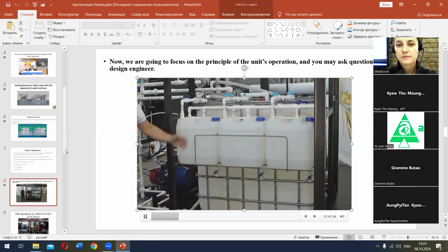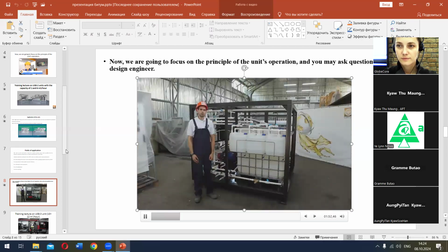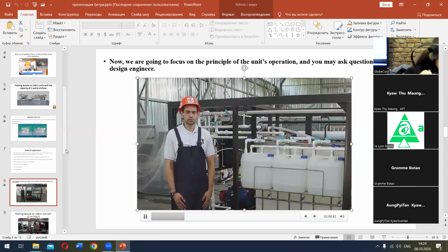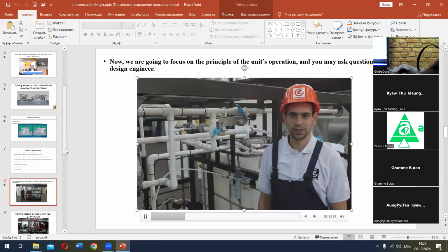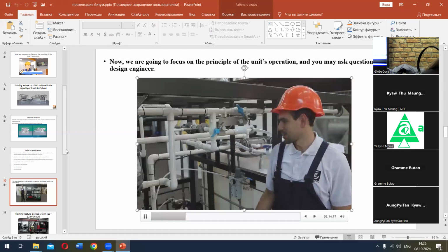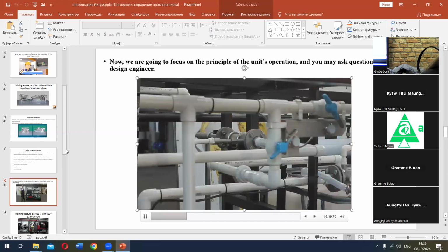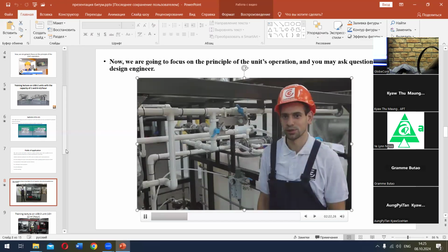The measuring tanks contain adhesion additive, emulsifier, and acid. The tank's content is fed through a hydrodynamic blend mixer into our tote tank. For customer convenience, the measuring tanks will be equipped with a ruler which makes it easy to monitor the flow and feed of liquid into the tote tank. Exiting from the water phase, the processed liquid enters a hydrodynamic mixer, which is a distinctive feature of GlobeCore units compared to the units from other manufacturers.